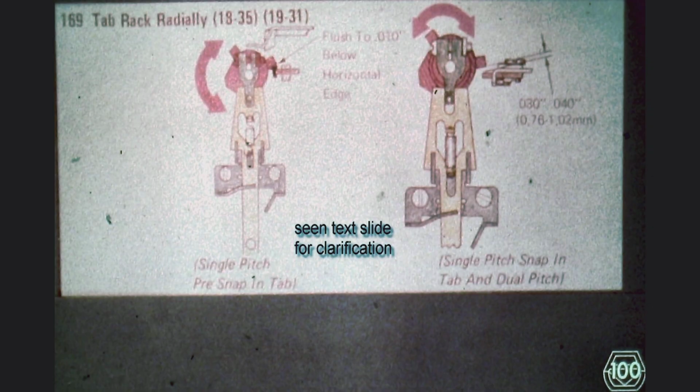We have also seen that loosening the tab set and clear clamp allows us to rotate the tab rack. We must position the tabulation stop rack so that at rest the tab stops clear the tab lever pawl, as shown in this adjustment frame. This adjustment establishes the angular rest position of the tab stop rack. It is important to know that in the figure on the right, the tab stop must be rotated counterclockwise, top to the rear, all the way, before we make the adjustment. Take a moment to check it out on your machine.